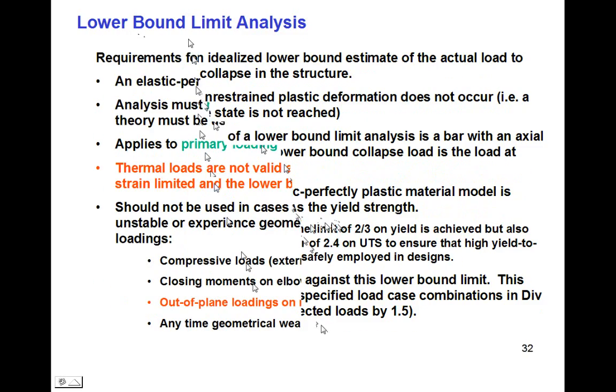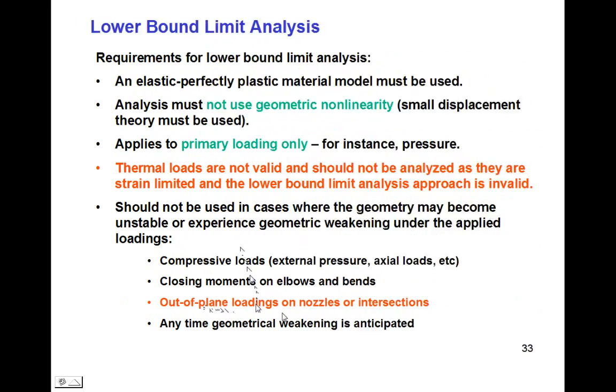Unfortunately, the lower bound limit analysis is not recommended for out-of-plane loadings on nozzles or intersections, or combinations of pressure with out-of-plane loadings on nozzles or intersections. So when we're interested in the combinations of out-of-plane loadings on nozzles and intersections with pressure, we can only go back to the elastic plastic analysis.